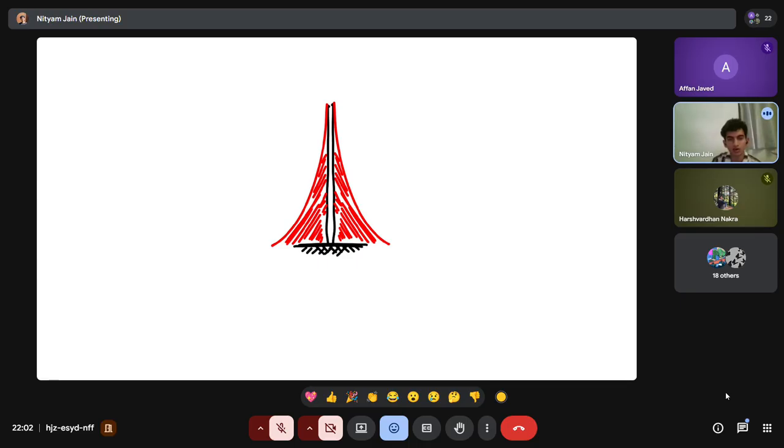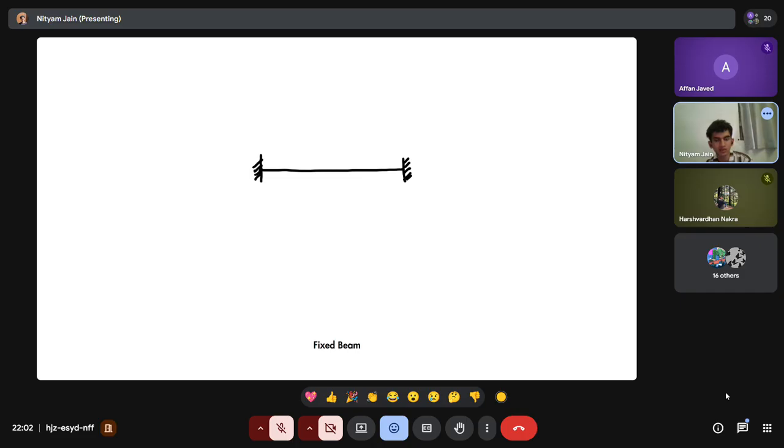If we just imagine it like a cantilever from the ground, like a vertical cantilever, the same thing, if we mirror it, we almost get the form of the Eiffel Tower, which is how it was derived. Because if it's a cantilever, there would be lateral forces of winds and everything acting on it. So to tackle that, it's made as a diagram of the bending moment.